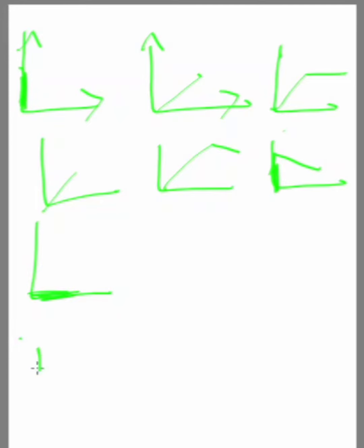In this graph, when carbon content increases, the x component will decrease, ductility will decrease, toughness will decrease, and the y component increases, strength increases, and brittleness also increases. Just study what ductility, brittleness and toughness are. And for brittle material, this is for compression and this is for tension, and there you will use proof stress or 0.2% yield stress.